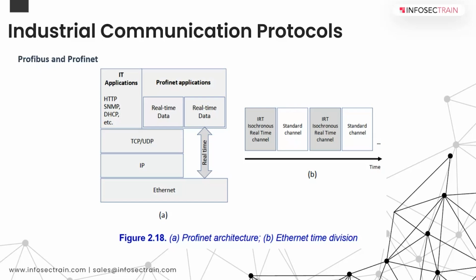It is a master slave protocol similar to Modbus, but a bit more sophisticated, with a procedure to join the network and time validations. These are very important aspects, right? In manufacturing or other industries, you have certain requirements, especially time sensitive, critical, and deterministic aspects, when you're dealing with real time data. So this helps a lot.